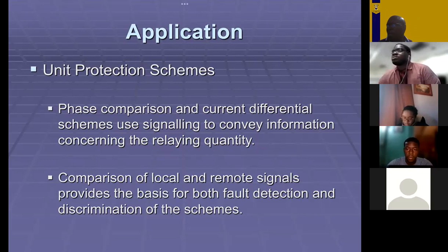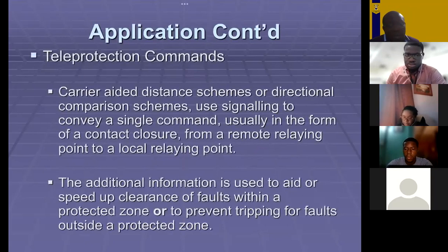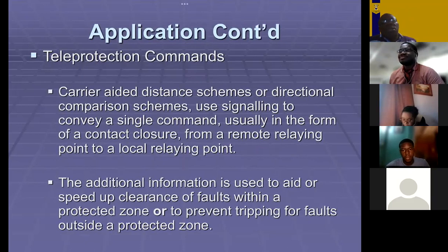In terms of what we were looking at last time, I put them together and refer to that now as your teleprotection commands. So your distance schemes, and next time we meet, we'll talk about directional comparison schemes, they use signaling to convey a command. And that command is usually initiated in the form of you closing a contact.